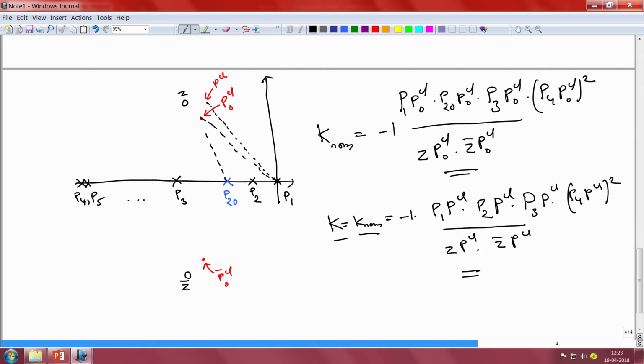On the other hand, the distance between PCL and PCL naught is expected to be just less than 0.04 units, which is almost 2 orders of magnitude lesser than the typical distances between the other open loop poles and zeros of the plant and the controller. Hence we can conclude that P1 PCL is approximately equal to P1 PCL naught.